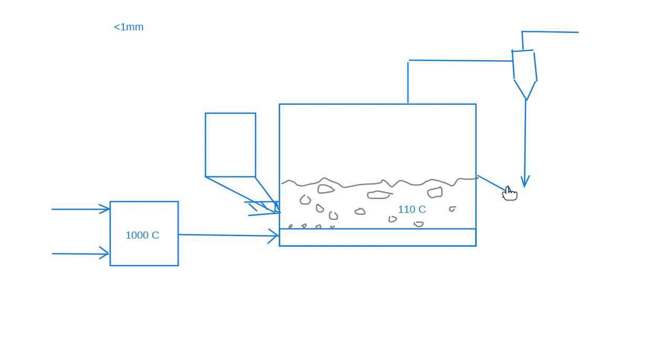So everything that's coming out here, a fluidized bed is very well mixed, so you will have the same temperature everywhere throughout this fluidized bed, and the gases that are coming out here will also be at exactly 110 degrees C because of the excellent heat transfer you get in a fluidized bed. So this stream coming up here is 110 degrees C, that stream is 110 degrees C, this stream is 110 degrees C. And then you're losing gas.